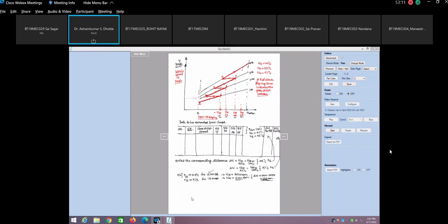The same thing happens if you keep your leg on the clutch pedal and drive the vehicle in half clutch, because for achieving the same RPM, if you are putting your leg on the clutch pedal, you are slightly disengaging the clutch, and then 100% power transmission will not be there.